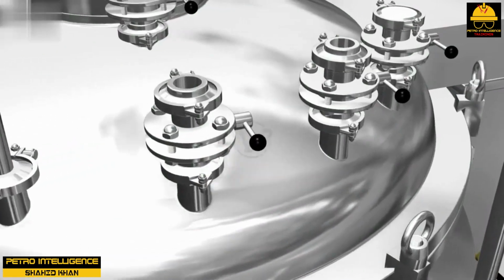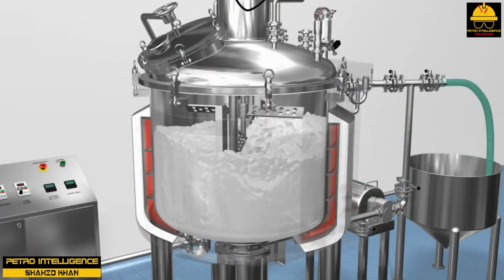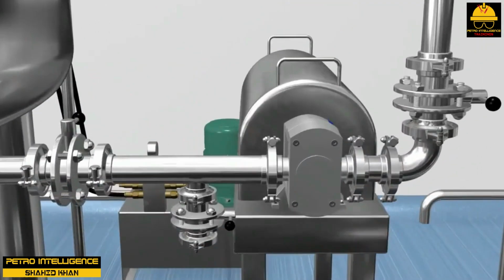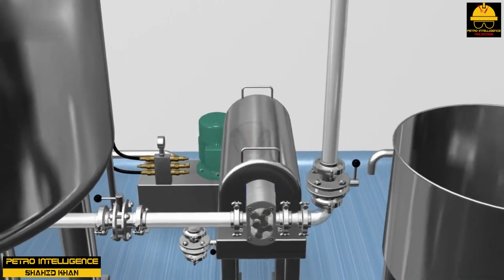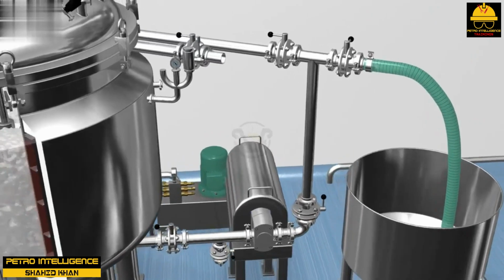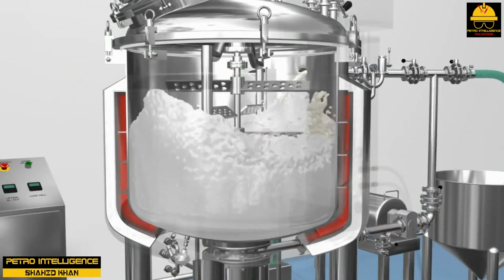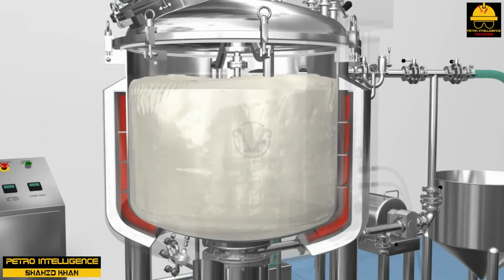Such reactors are also used when the production rate is to be variable and several different reactions or products are to be made in the same reactor. The early research and development of most processes is conducted in batch stirred reactors because of their versatility. Other considerations that must be taken into account are how much agitation is required to produce a uniform reaction mixture, what type of heat transfer equipment will be needed to prevent excessive fouling of the heat transfer surface, the minimum size of reactor that is needed to obtain the necessary reaction time, and whether a catalyst is needed to promote the reaction and how it will be added to prevent a localized reaction.